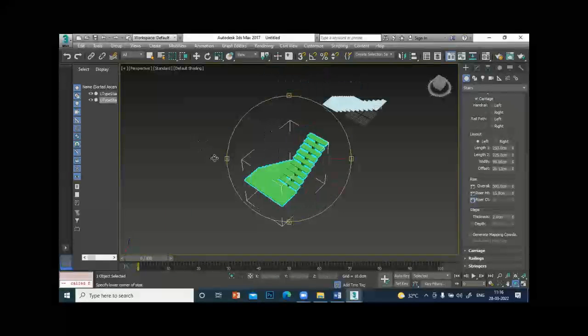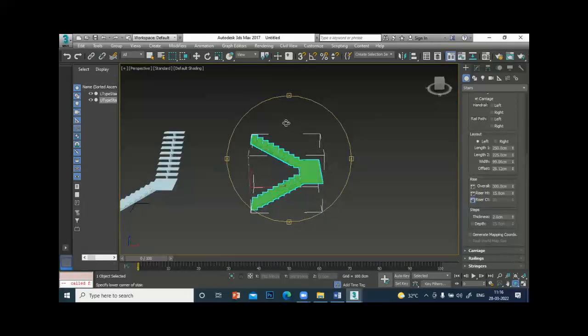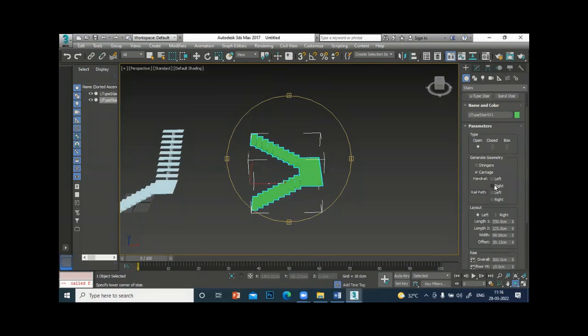Now we got some idea. And here also we can have the handrail if you want, rail path. Then you go to railing and select this one. You get the handrail automatically. Then you have to move it down, touching the steps. You can adjust that. You can try that.